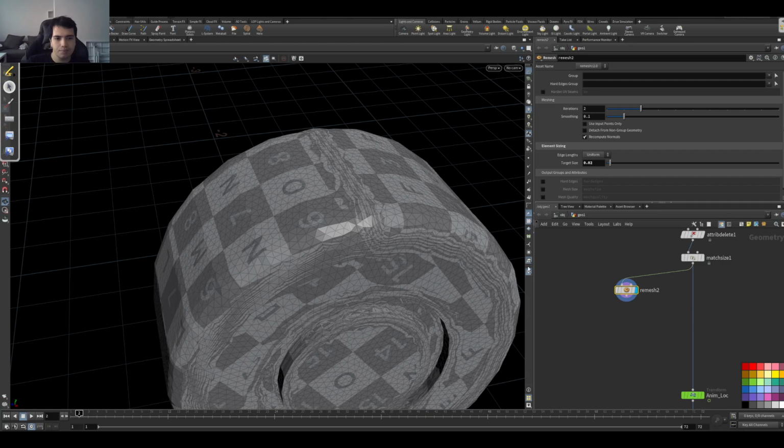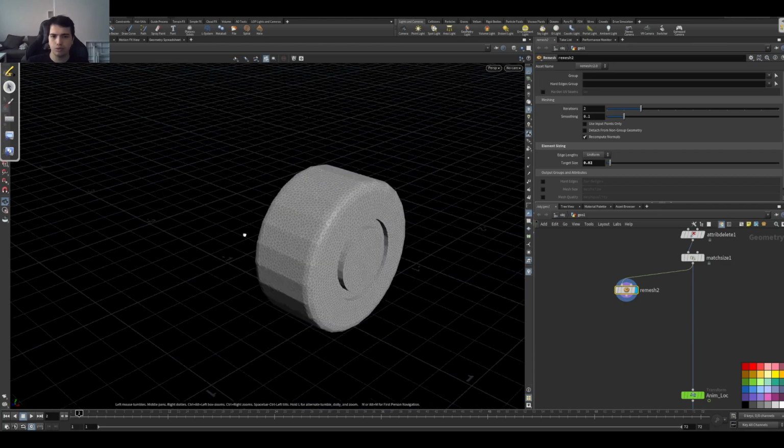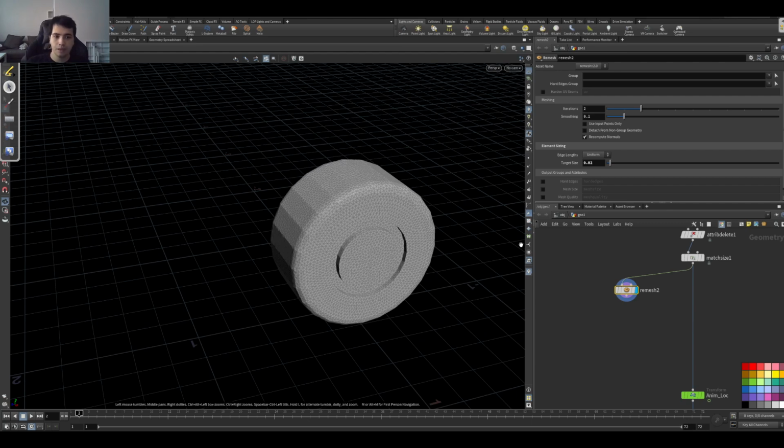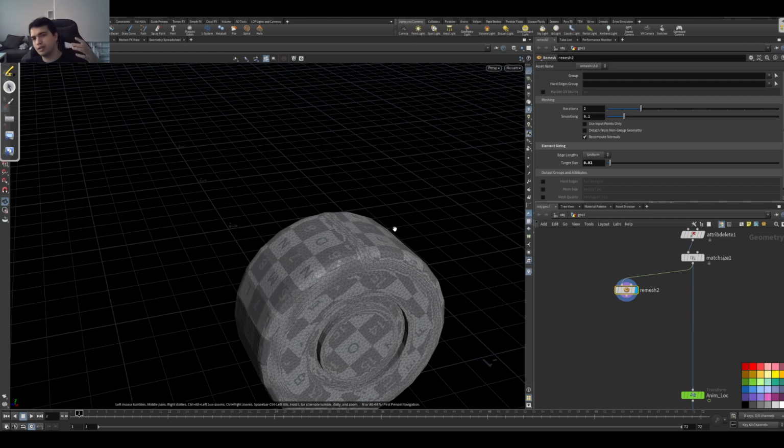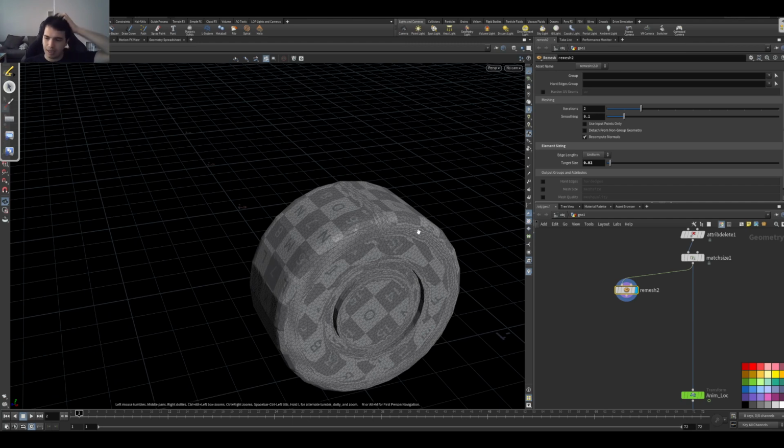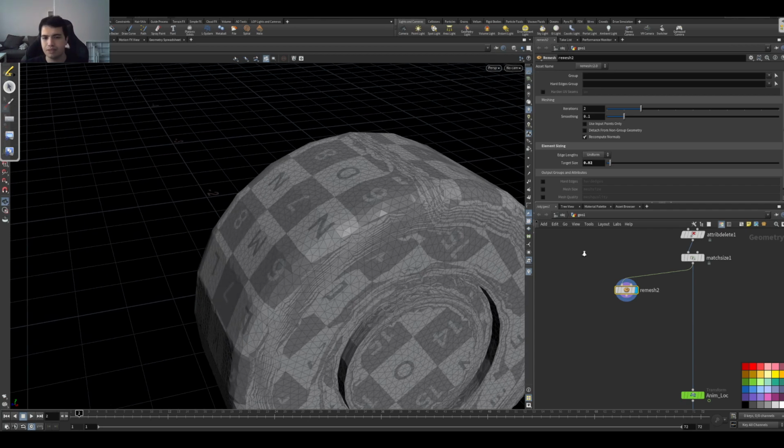Although I might not see a problem if I don't use my UVs, you can see this, it's okay. But in the rendering phase, my textures won't be usable, or I can't use other outsourced noises, etc., because my UVs are distorted. I need to use a hard edge group. Now you see this hard edge group. What does it do? The edge group that you give stays still, and as there won't be any middle points between them or any deformations throughout that edge, your UVs will be preserved better as well.